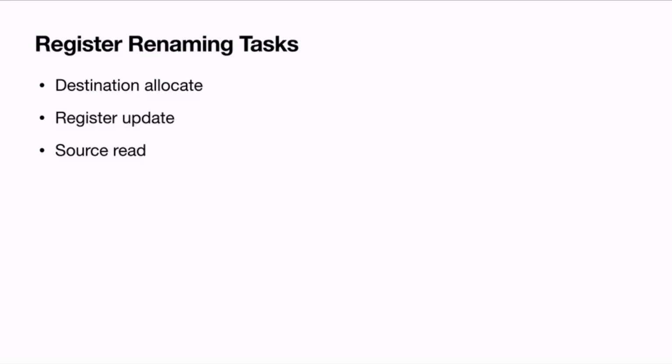When I say an instruction finishes, it may be because I am executing instructions in an out-of-order fashion, right? There may be many prior instructions which are not yet committed. How can I write directly to R1 now? If I write to R1, and any of the previous instructions creates an exception, I have to roll back, right? But if I have already written the value into the R1 architectural register, then your checkpointed state is wrong, right? If there is an exception or something happens, you have to roll back to the previous state.